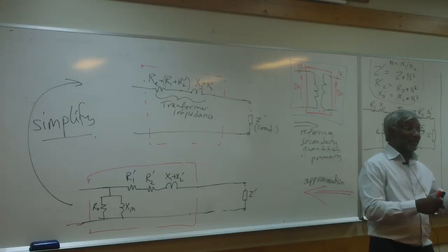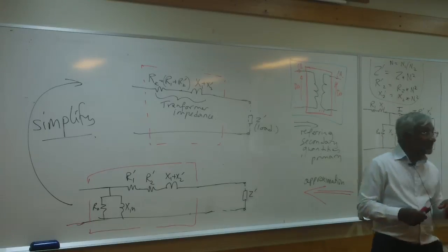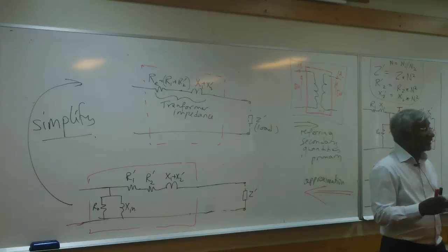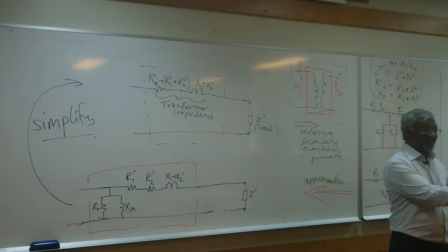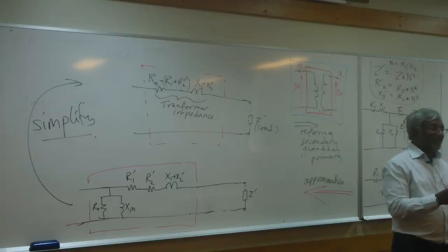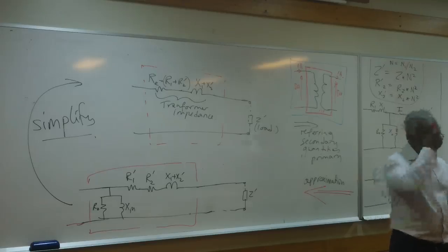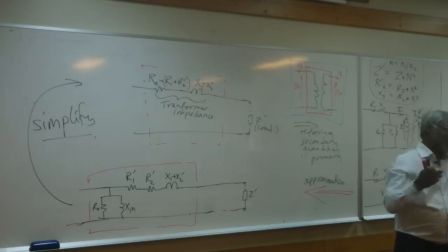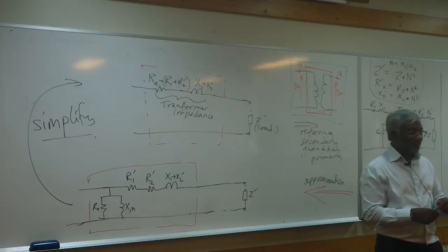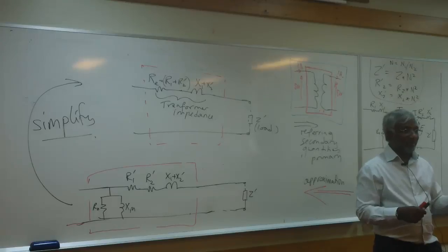So for redundancy. And when you're supplying an important city like Toowoomba, we don't want it to go blackout because one transformer had a fault in it. So to prevent the blackout for important people living in Toowoomba, like us, we would like some redundancy at the substation. So at the substation, we have two transformers connected in parallel, feeding the city of Toowoomba and, of course, other cities. And if one of those transformers was in trouble, then the other one would take up the load.